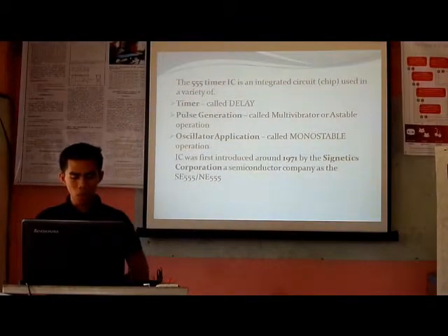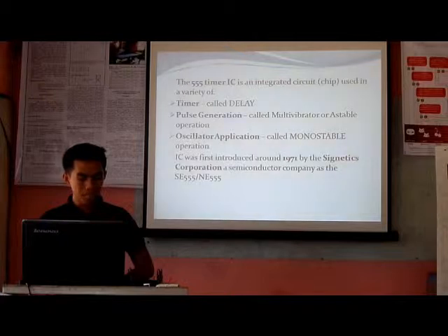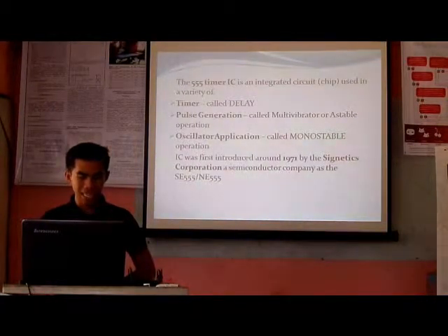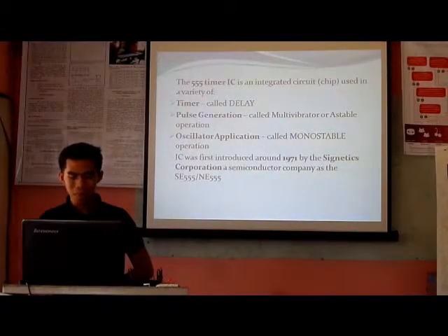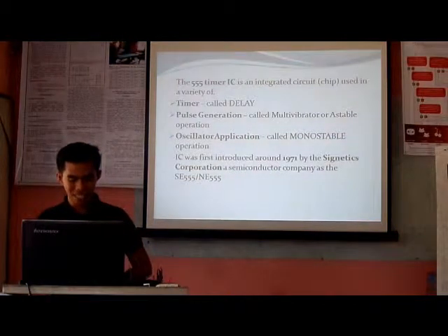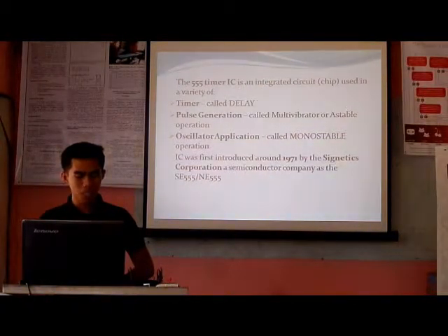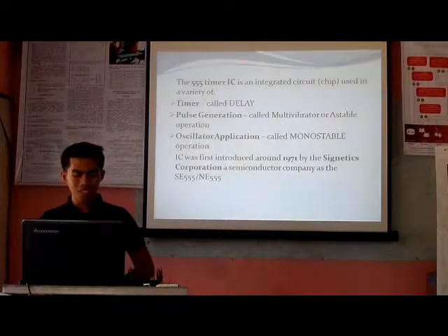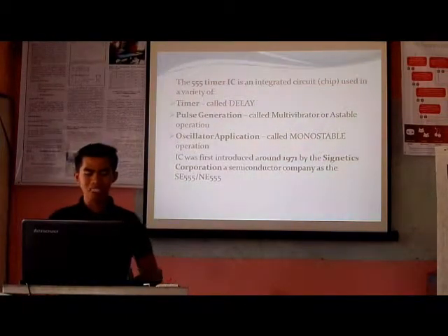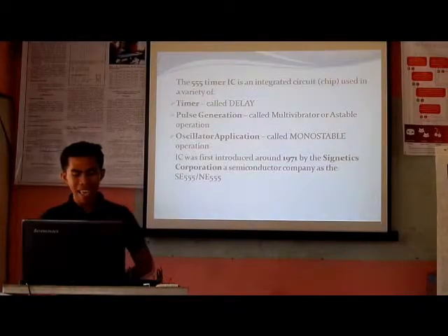These were available in both high reliability metal can, or what we call the T package, and inexpensive plastic or V packages. These full part numbers were NE555V, SE555V, and so on.